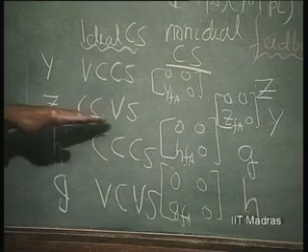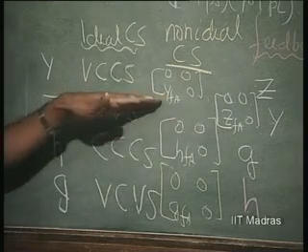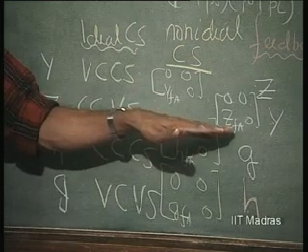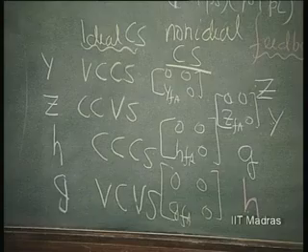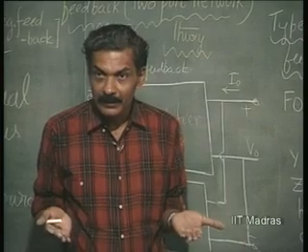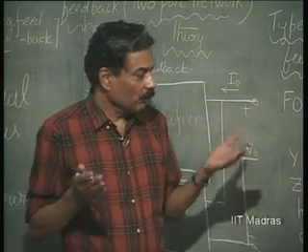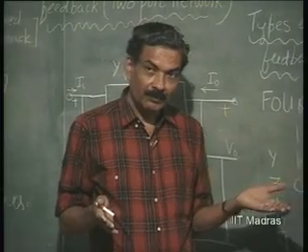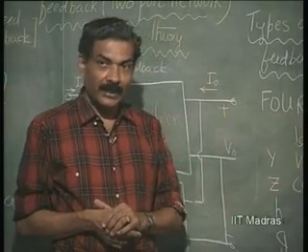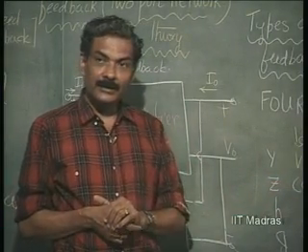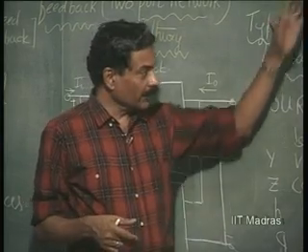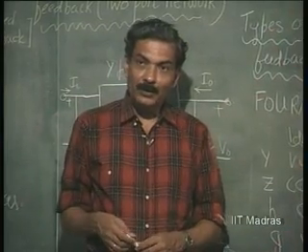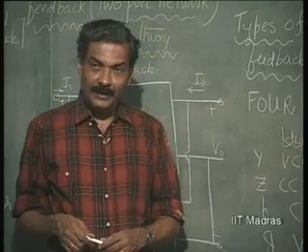Again, if it is Z or Y feedback, corresponding to impedance and admittance, the bandwidth is improved, may not be for the gains. So this is what is to be digested clearly before we go further with specific examples on negative feedback, as long as you have understood the two port network theory involving negative feedback.